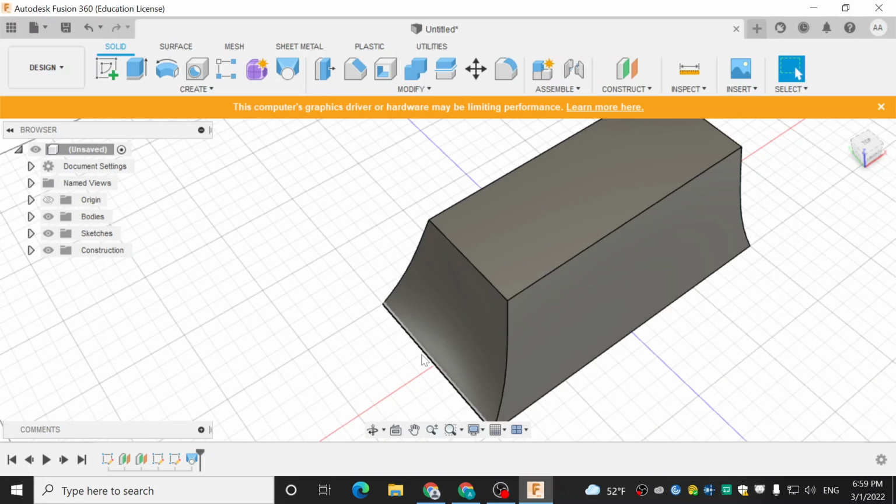If you wanted to have more, you can add more rails. We drew that on the center plane. If you wanted a rail that connected the edges, you could draw on the other center plane here. And that way you could get another perspective and add rails on the other side.